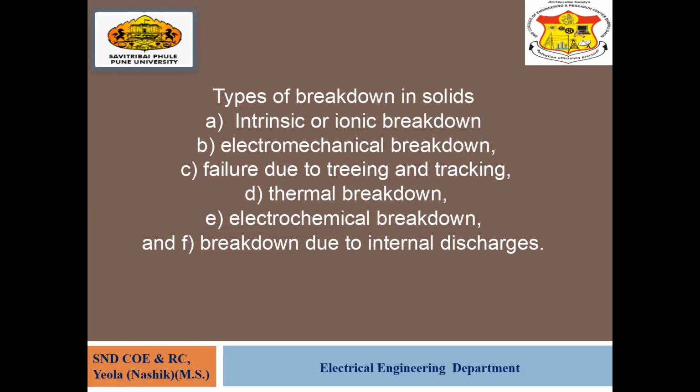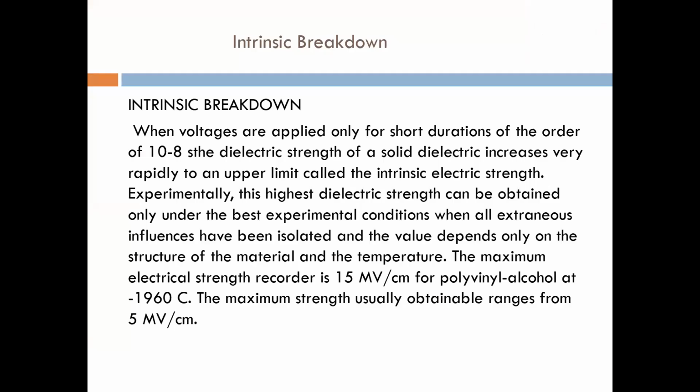Step by step, we will see the intrinsic breakdown. In this case, suppose the voltage is applied for a very short duration, such as 10 raised to the power minus 8 seconds. Then the dielectric strength of the solid dielectric increases very rapidly to an upper limit, and that limit is called the intrinsic electric strength.